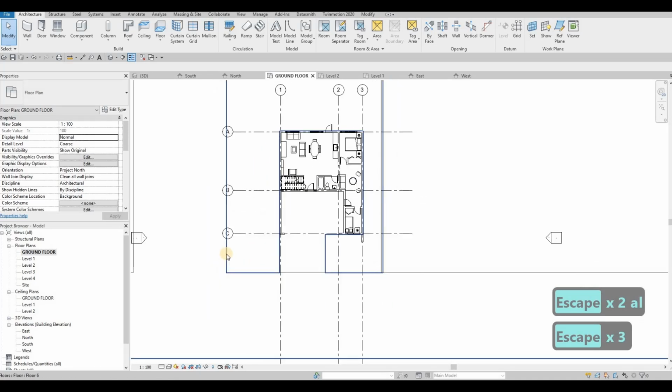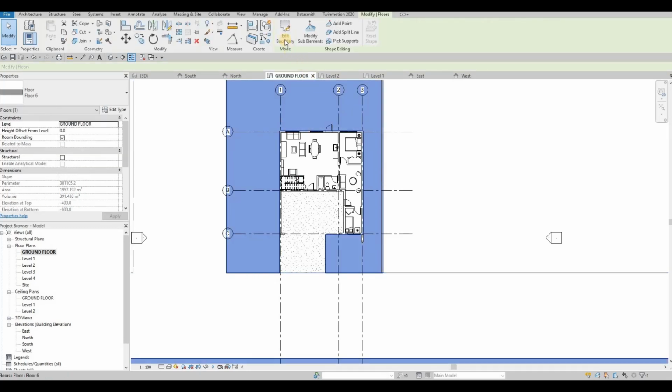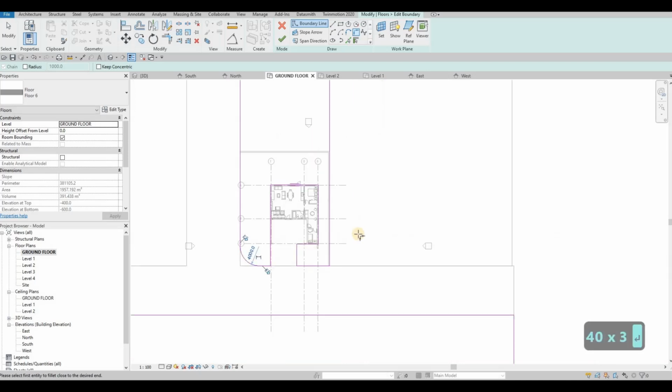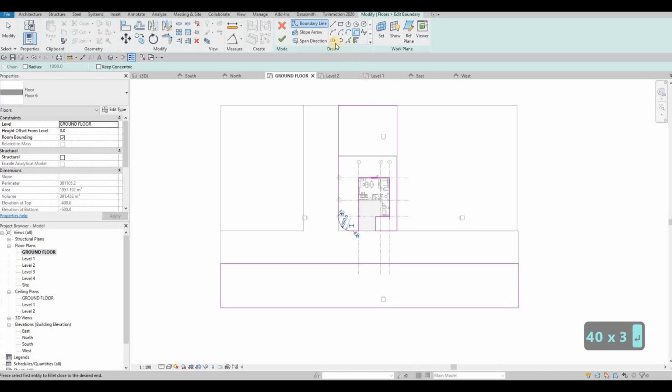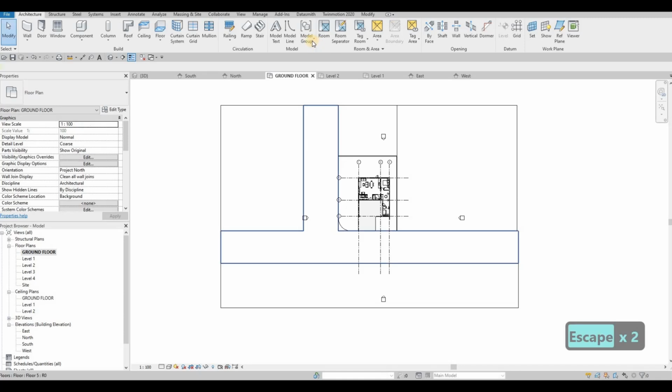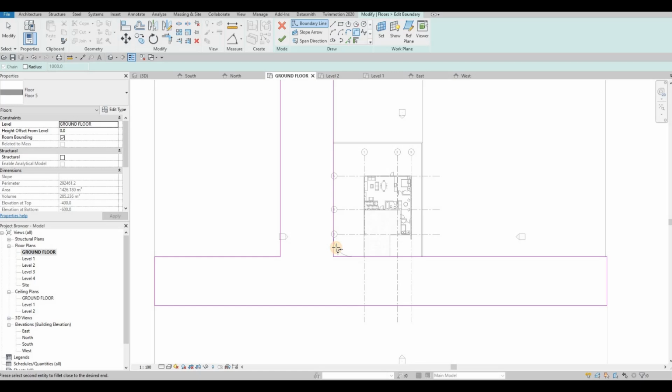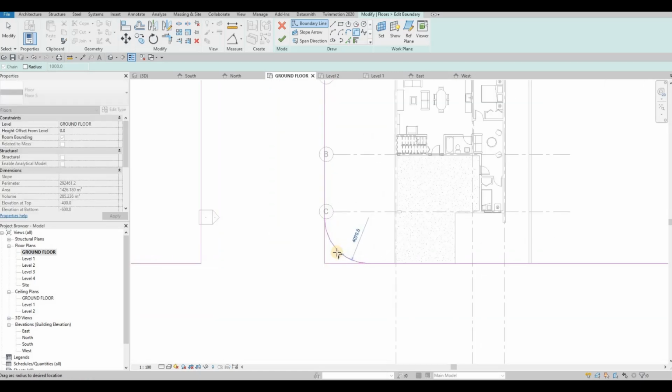There we go. And then I'm gonna curve this so that it looks nice. So definitely going to curve this. Edit, fillet arc. I'm gonna use probably, make it 4,000. Okay, so that's the side there. And then of course we're gonna edit here as well, so we're gonna maintain that 4,000, but it's gonna be easier for us because we have that one.